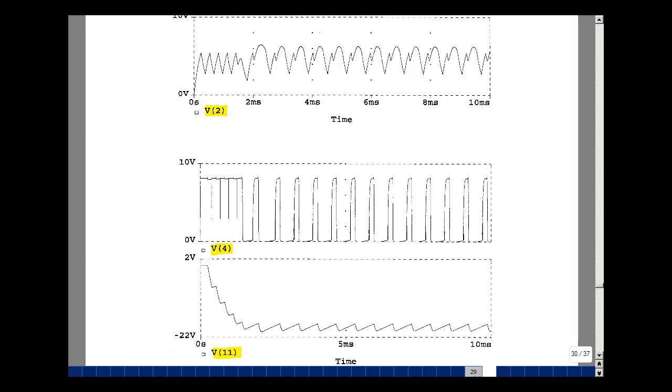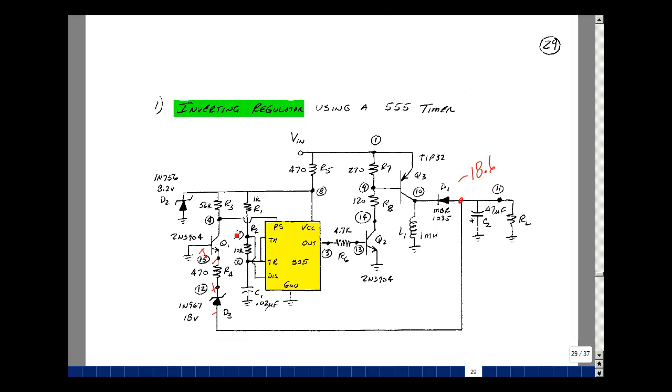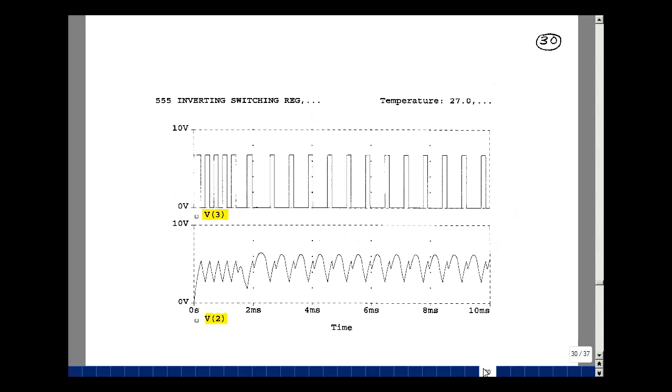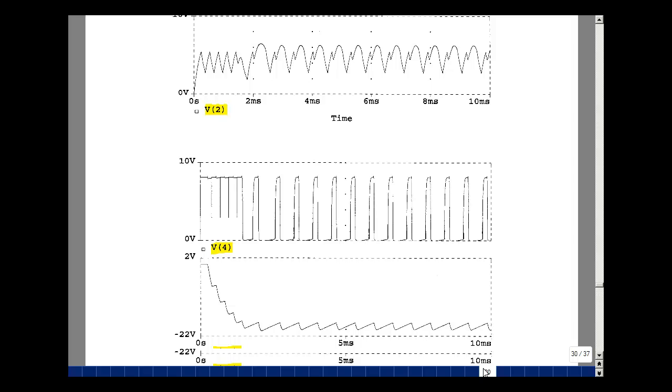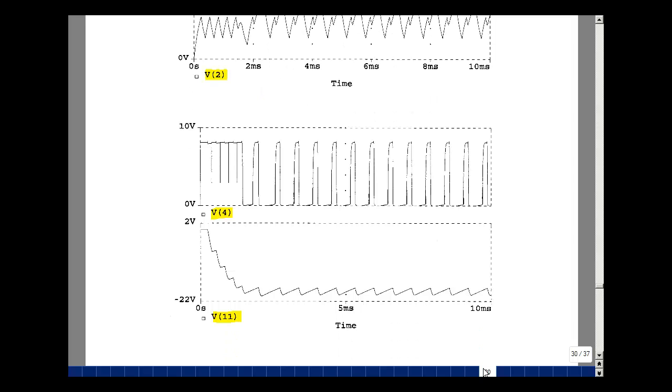We go back to the picture here. This saturates, then this node voltage is going to be, say, roughly 0.1 and then minus 0.6. So it'll be slightly negative on the low side of that reset waveform. And then lastly, here's our output across the capacitor and the load. And you can see here there's a ripple and then eventually a steady state value.